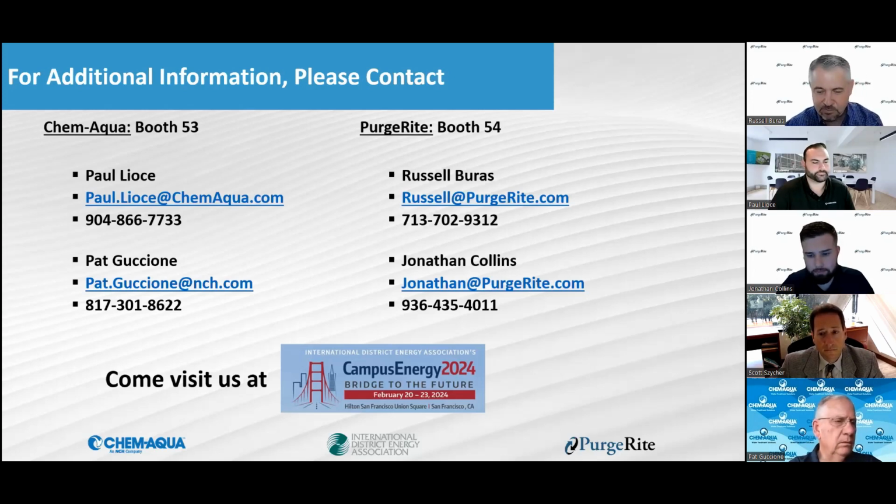Sometimes they're combined, sometimes they're not. And it will speak to the chemistry side of it. A lot of things Paul touched on, like they want it circulated for a minimum of 48 hours, or it may say we want it flushed at 10 feet per second for so much duration. So we look at that, and then we look at the mechanical drawings. We look at where we would connect our equipment, how we would connect our equipment, and then go back into all those calculations for flow to maintain a certain velocity throughout the system. What bypasses do we need, valves, etc.